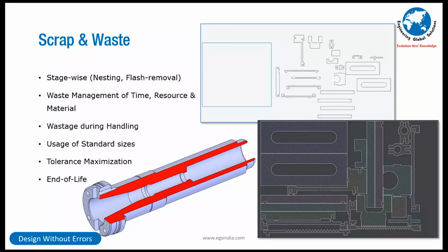So when you're doing new product development on another part, you go back and say, hey, there was some material already available which is going into scrap. I'm going to use that material and include this part in it. So I will use the same sheet metal thickness, the same grain direction. I will reinforce it and use these materials so that it keeps filling up, so that my piece scrap keeps coming down as more and more products are produced by me. So don't look at it as a one-time occurrence. This needs to be done throughout the new product development that we keep doing in our office all the time.